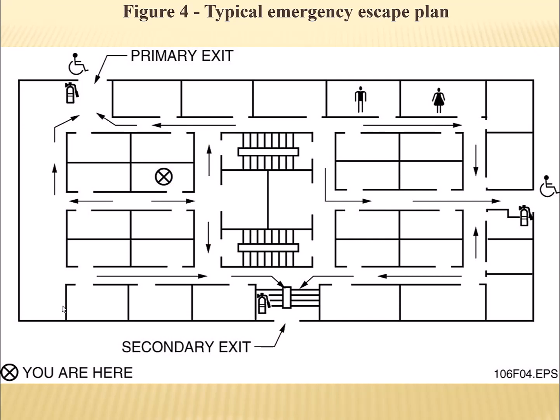Okay, so even in buildings like our classroom, the buildings our classroom is in, just to get the final building permit to build the structure, you've got to have an escape plan that is all planned out. You've got to assign how many people can even officially be in any particular room. So our regular classroom for this class, in room 116, has a rating of 40 people. So literally the fire marshal, if they were to come and find you had 50 people in there, they could shut the building down and issue you a citation and fines. So that can happen.